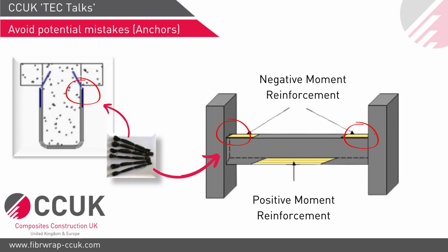The other thing is the use of these anchors in shear strengthening. So usually shear strengthening is done like, imagine putting a link or a stirrup from the outside of a beam. Yeah. That's why it's called U-wrap strengthening. So again, in that as well, obviously you cannot use plate system there, so you will use fabric system. So what people do is they just apply it like a U-wrap.